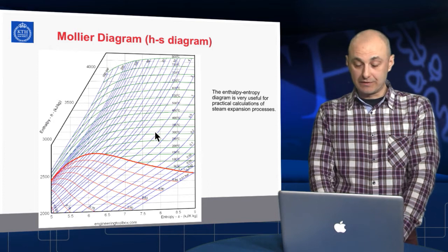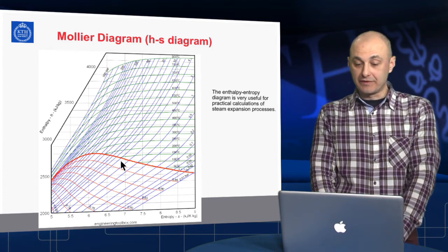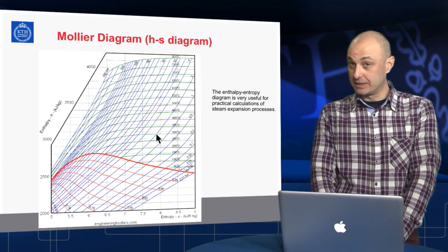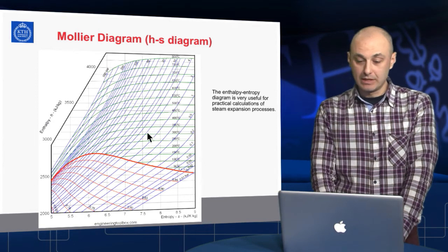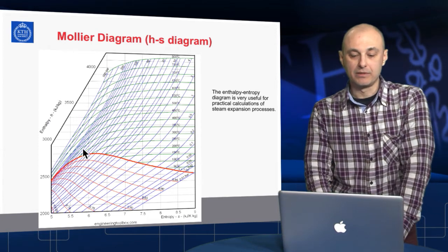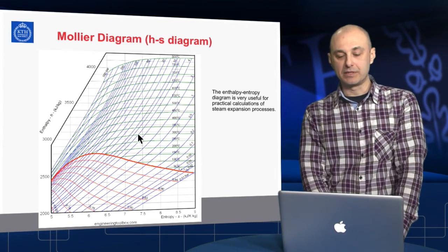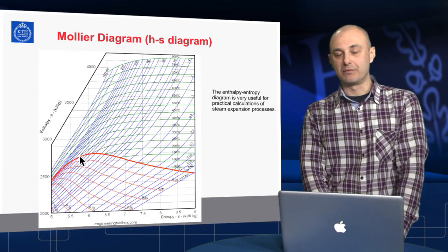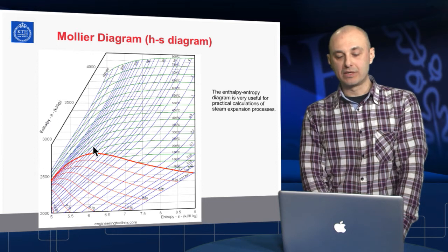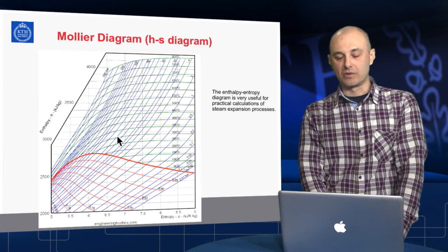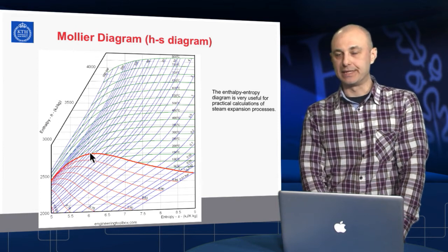And it is not a straight function. It is actually quite difficult to represent analytically. This is easily seen by the fact that the constant temperature lines in this diagram, represented in green, are actually curved. There is a complex variation in the position of the temperature lines as long as we get close to the double phase dome. The more curved it is, the more we get close to the double phase lines.